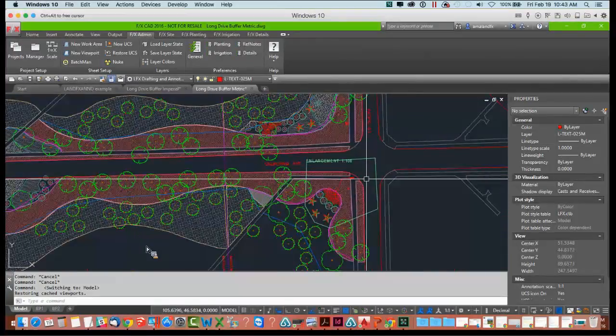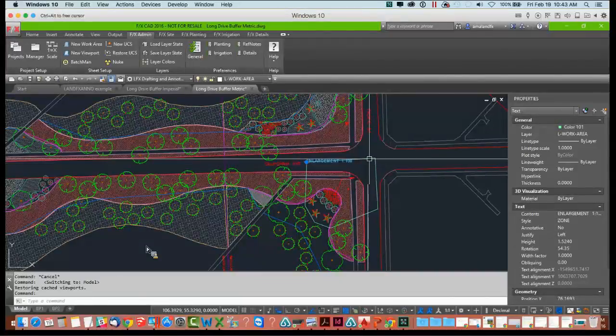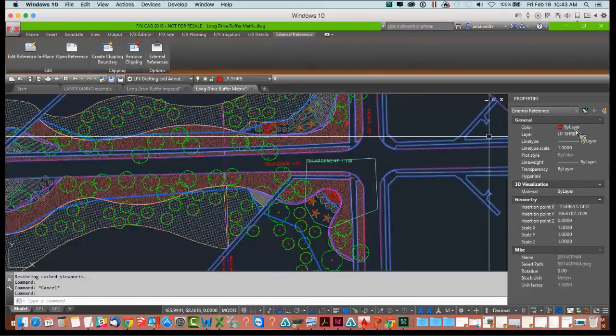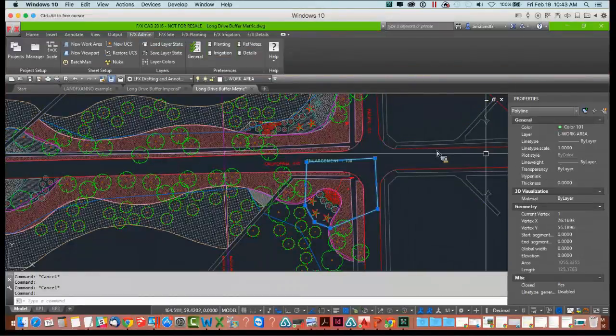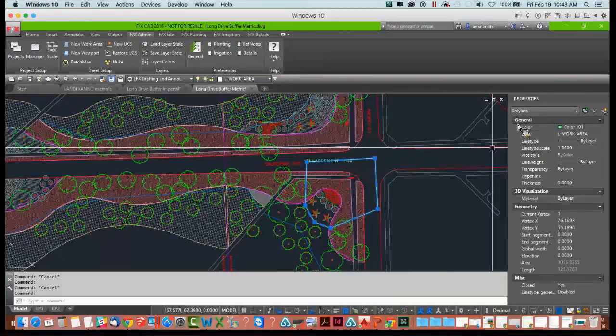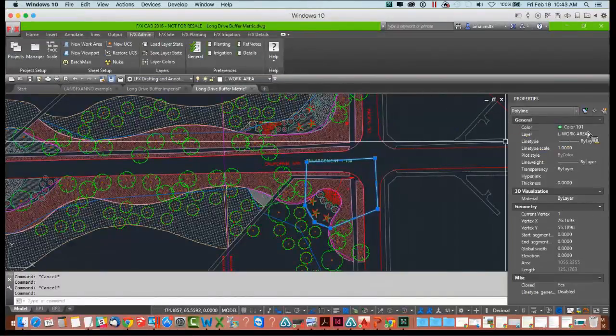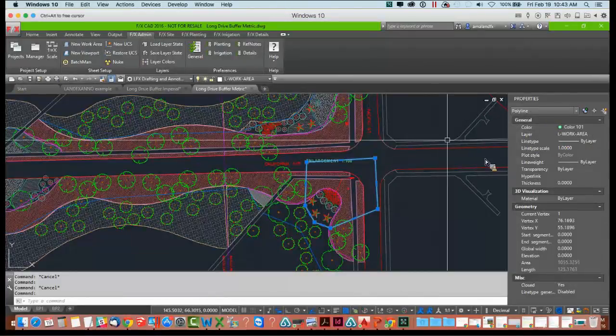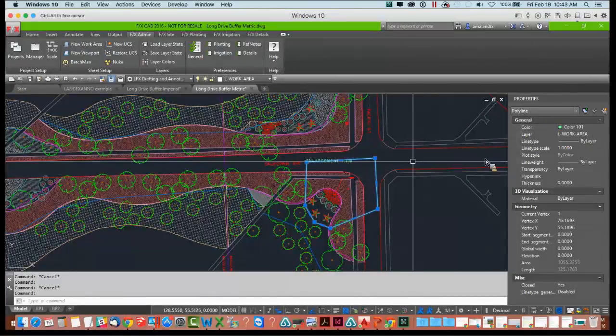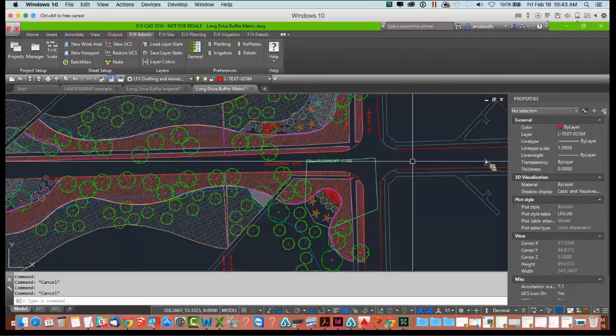Just make sure that the XREF is set on the layer for work areas. So instead of putting an X reference on an X reference layer, you would put it on the same layer as you have for work area. So you would assign the X reference to the L work area layer, or whatever layer your work areas are coming in on. I believe the other one was LP Anno border, the old one if you have an old installation. Both will work. Just make sure that it's set to that, and any X-referenced work areas will be included in all of this.